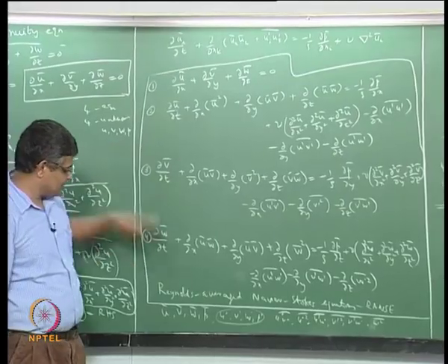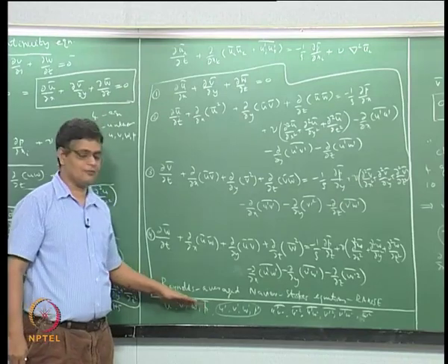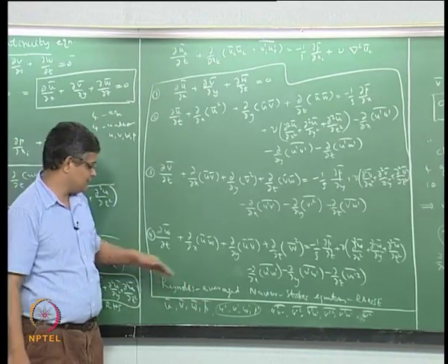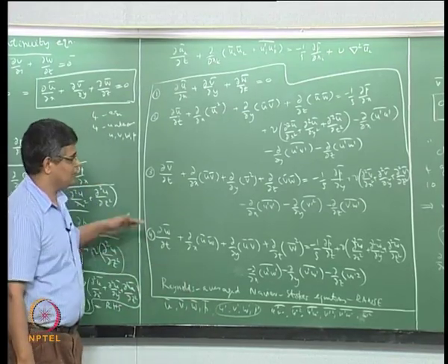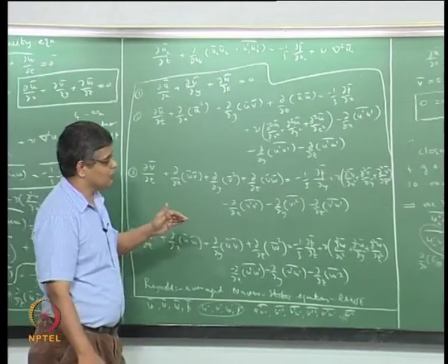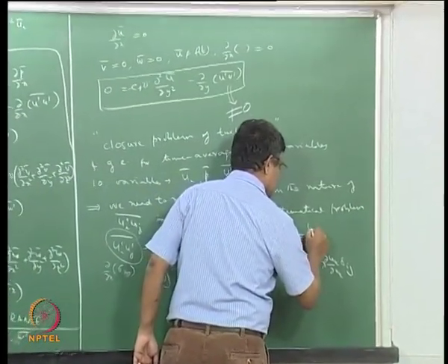And variables of interest are the time averaged velocity components and pressure, from which we can get time averaged drag coefficient, time averaged pressure gradient and so on for a given flow rate. So this is what we need to do, and this is what turbulence modeling is about.